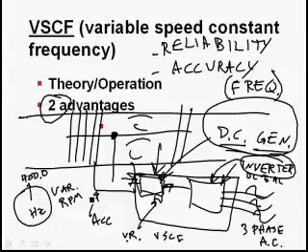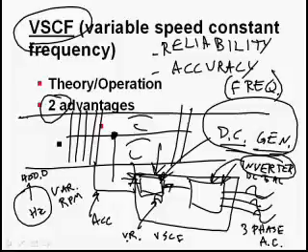It's so good. So there are some airplanes that don't have IDGs, or they don't have constant speed drives with AC generators. They have VSCFs. I know there is a model of 737 at a minimum that you can get, I don't know if it's an option or standard equipment, a variable speed constant frequency device on it instead of a CSD and instead of an alternating current generator.